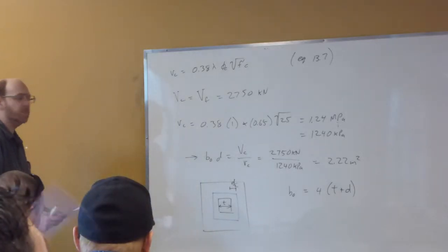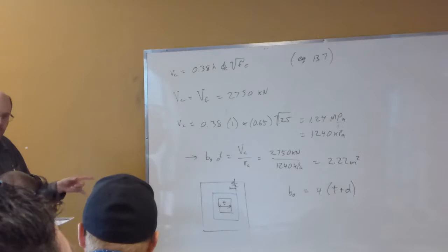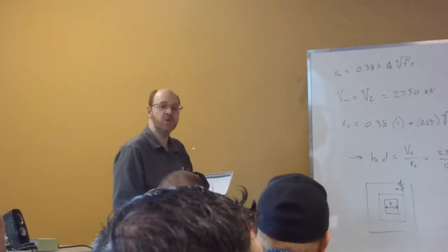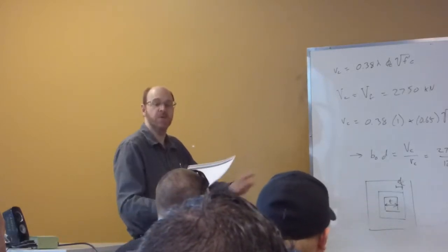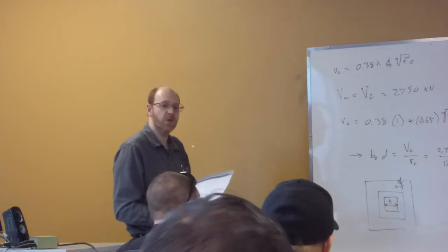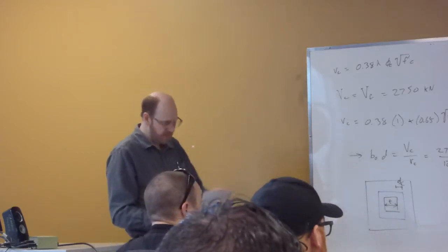So for a wall, you have on the left side 2. For a wall, we don't have two-way bending. Oh, yeah, that's right. So for a wall, we just go straight for a 1 meter wide design strip and do it like a slab, and we're just calculating our one-way shear only. Right, so now I know D.